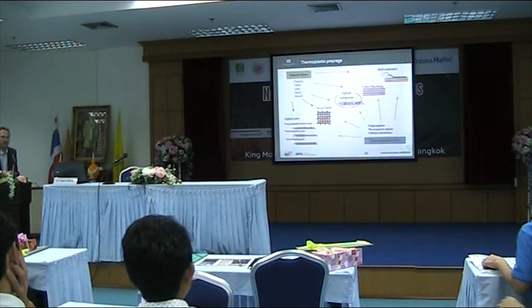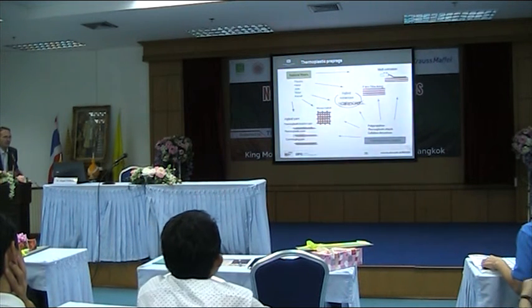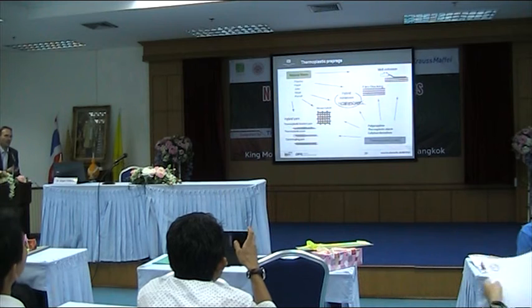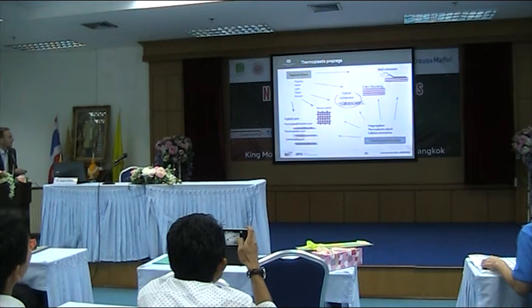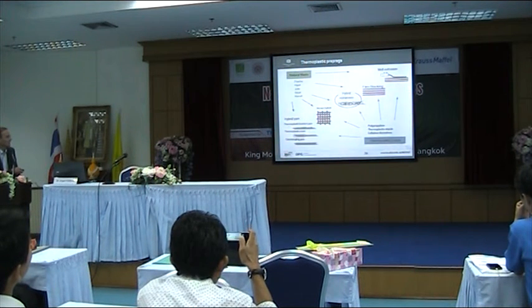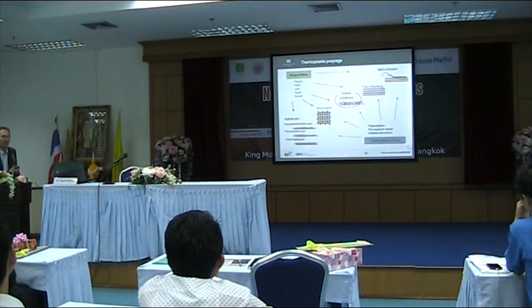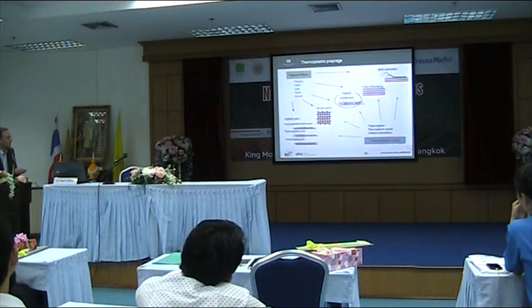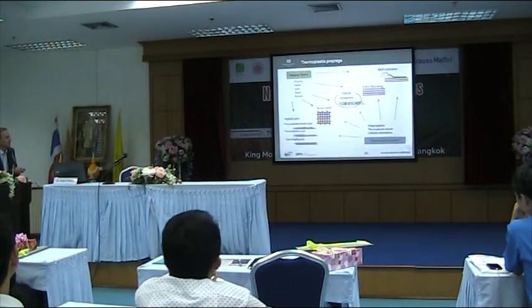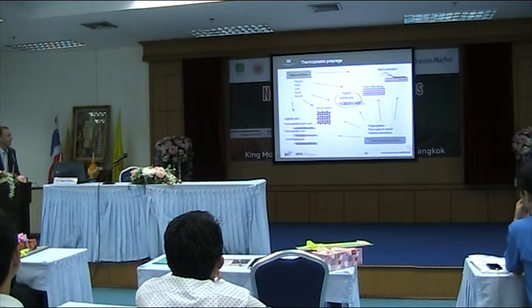So you have a woven fabric made from natural fibers with some matrix fibers, for example polypropylene or polyamide, thermoplastic, you can use. Also, you have hybrid yarn, so it's like a commingling process. You have polypropylene fibers, some natural fibers you can so-called commingle. So you always want to have the matrix close to the fiber, so you can reduce the flow lengths during consolidation. And these are typical prepreg materials you can use.